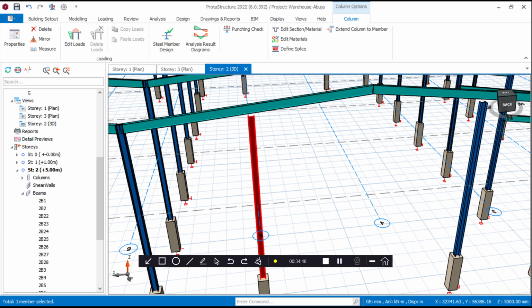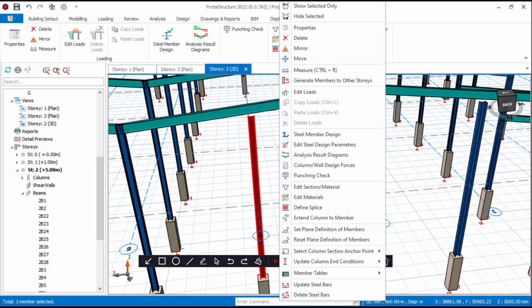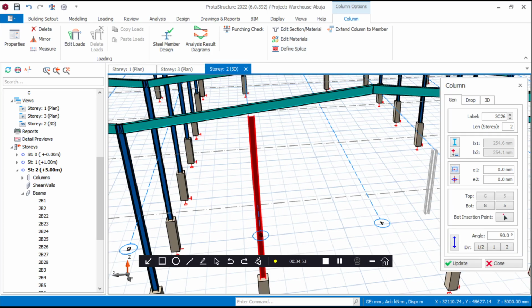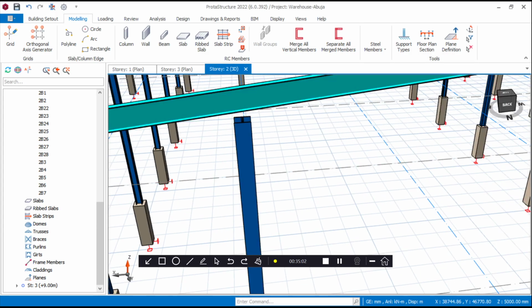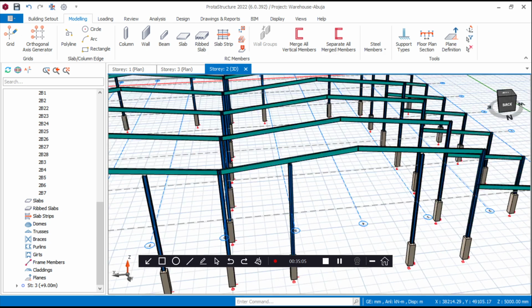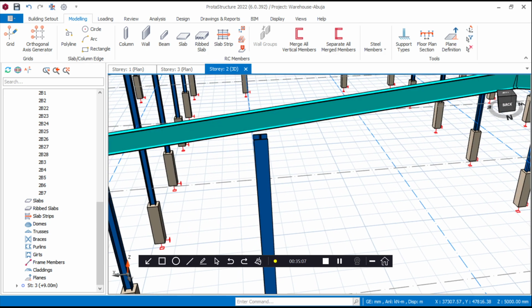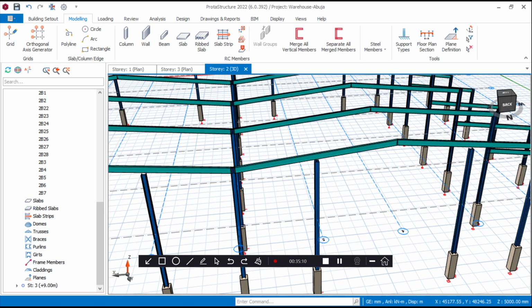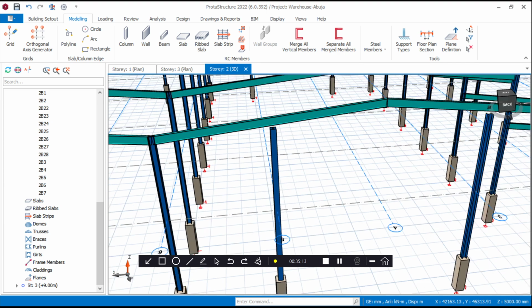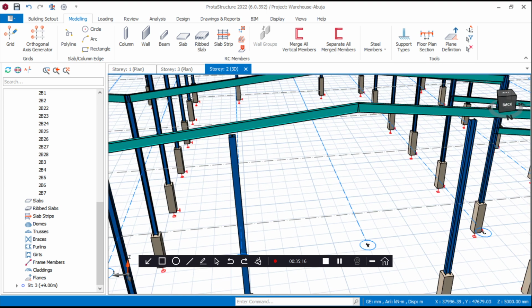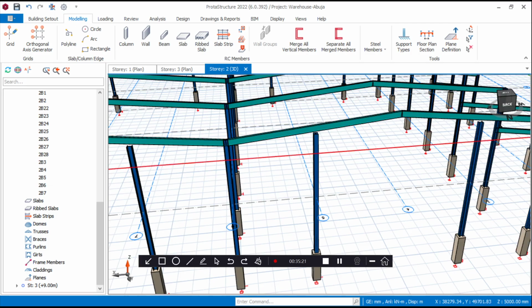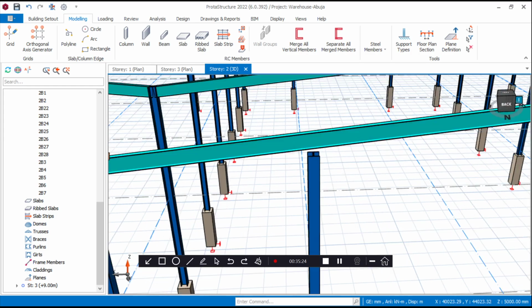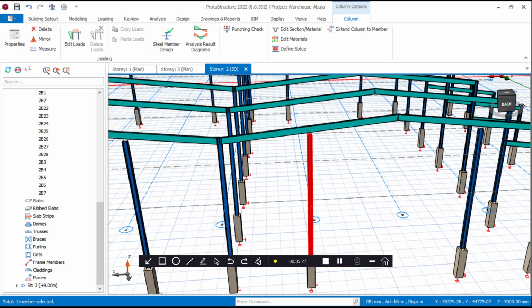Now for this, go to properties, let's rotate it to 0. We update. So you see that the orientation has changed. Now for us to take it up to the rafter, remember that from this place up is actually 1 meter. So the stanchion is already at 1 meter. Now you see that this one is like half of the 1 meter. So for me to take it up to flush with this, it is actually going to be 500.